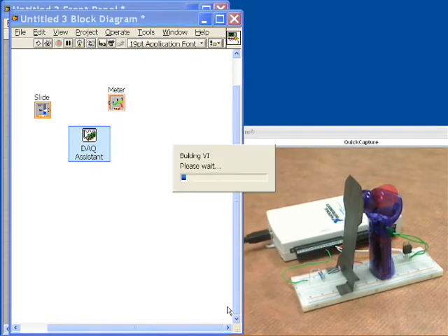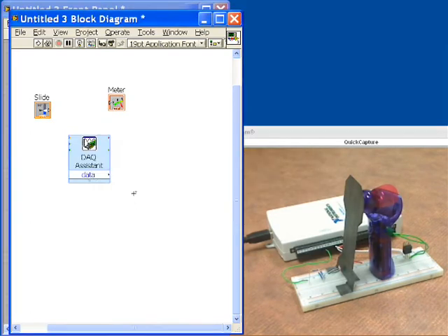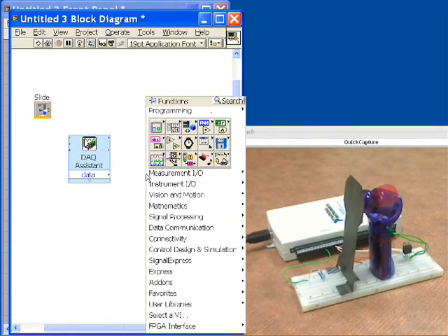Now at this point we're doing our analog input, and those are the values that we want, and it's working the way that we think it should. But I did notice that it was jumping around a little bit, and that's probably because of the photocell itself or changes in the light. So I think we'll put a filter in between this to smooth that out a little bit.